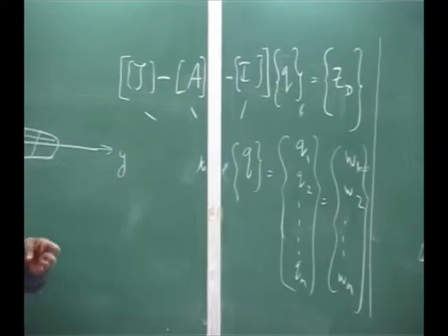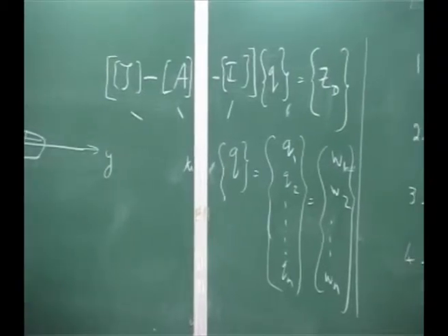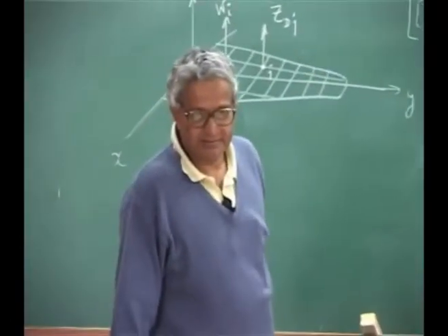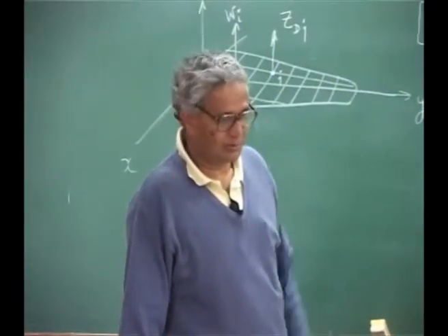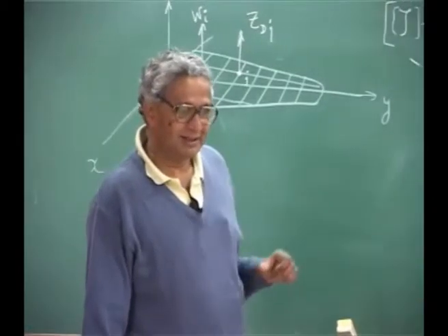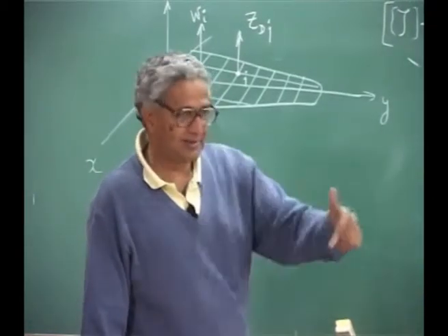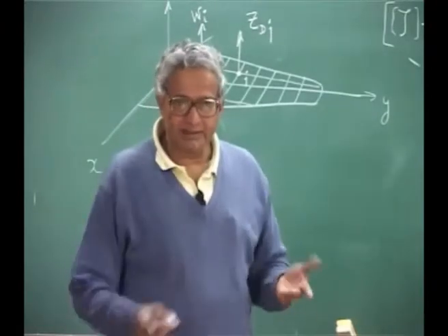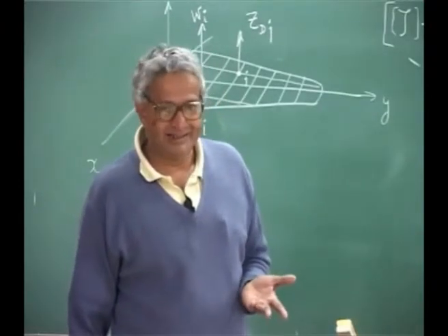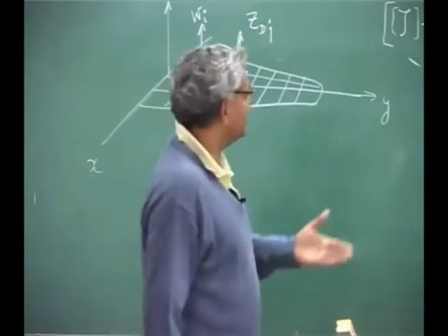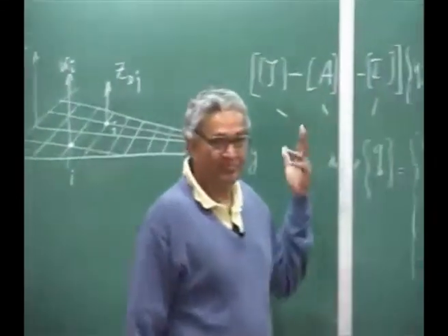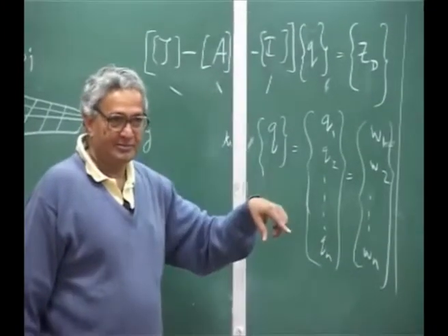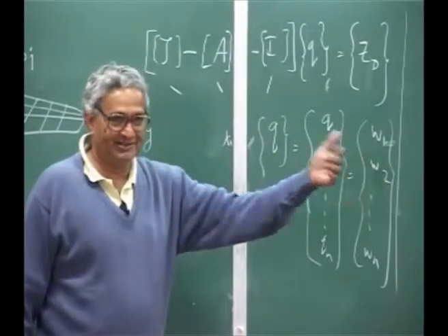That means, like I told you, you have the influence coefficient. You formulated it, right? You put a load in one place, you found the deflection at a couple of locations. That influence coefficient matrix, which you formulated, those are these matrices. You put a load, deflection, load, deflection.